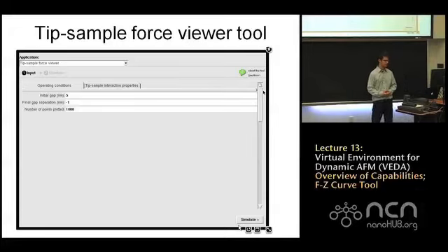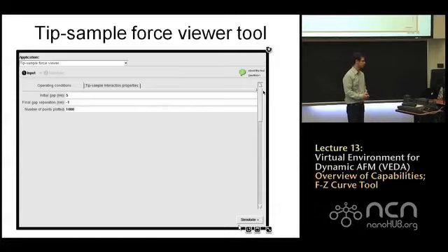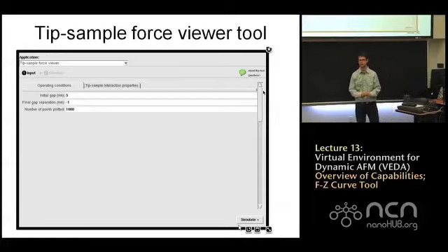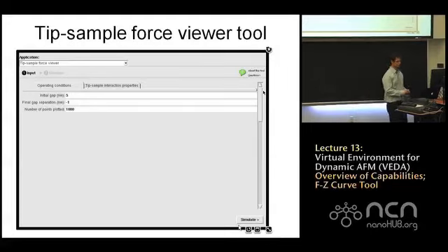Okay, so when we select this, you'll notice that there are tabs at the top of the page, and these have different input parameters on them. The first one that comes up is what we call operating conditions, and for this, I just want to change the input for the initial gap to 5 nanometers and the final gap to -1 nanometers from the default inputs. And second, if we select the tip sample interaction properties tab, you'll find...